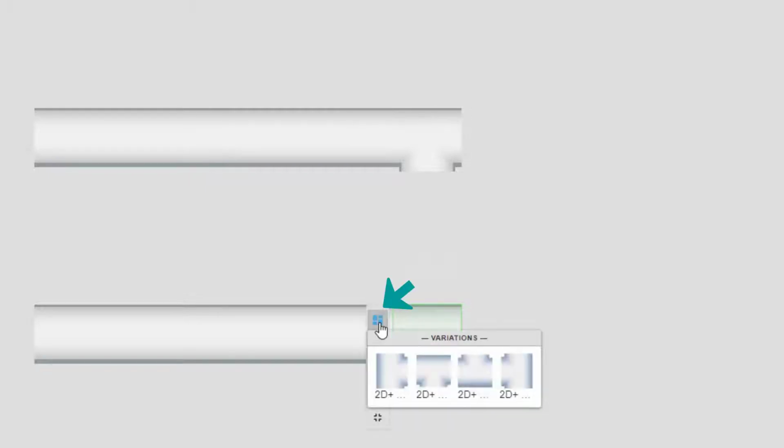Now, let's do a copy of this. You could either use the menu command, or Ctrl-C, and Ctrl-V from your keyboard. Again, drag the element. If it's now in a wrong direction, you can just click on these icons, and turn the element around. Let's continue with the ductwork.